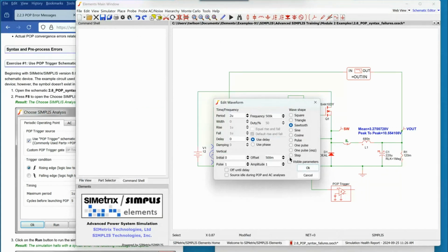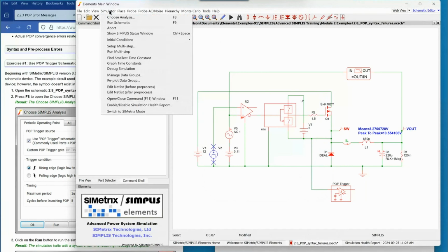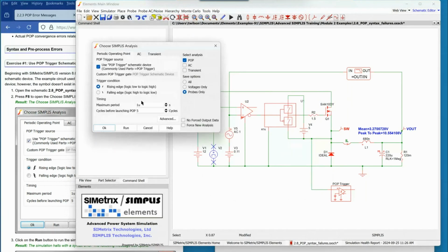So that's going to be a problem. So 3 micro then, yeah. What I like to do is put in something that, since this isn't variable frequency, we don't need to go too crazy, but I'll go 10%. Christoph can go 3. But remember, if I have those defaults set, I'm going to go to 100 switching cycles in my time domain, so I'm going to go 100 times this far before the simulation finishes, if it is a problem. So I like to try to make this comfortably large, but not too large.